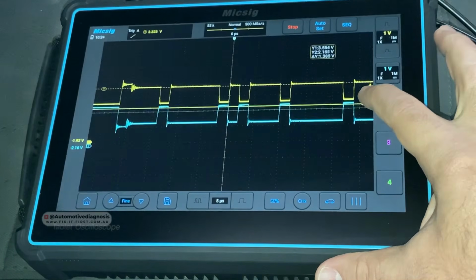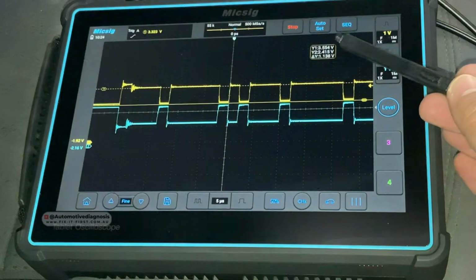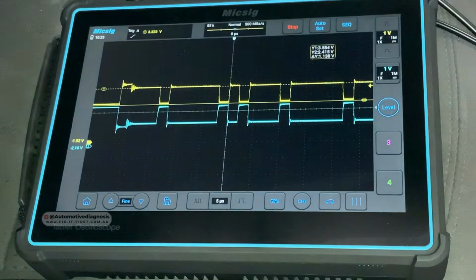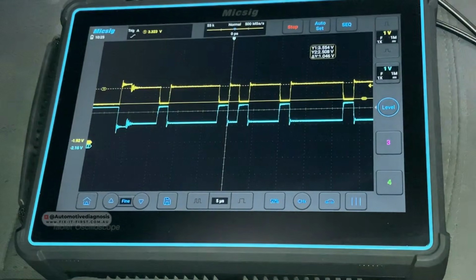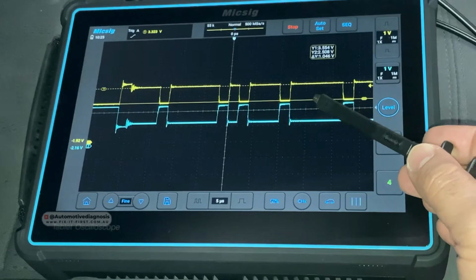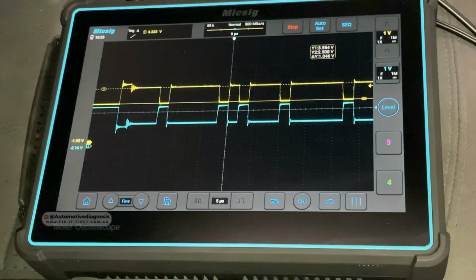And this one, the base voltage. You can read the voltage right now here. Y1, which is the maximum voltage, is 3.5, and Y2 is 2.5. So as I mentioned, CAN bus voltage changes between 2.5 on the base to 3.5 at this point. This shows the normal voltage range.